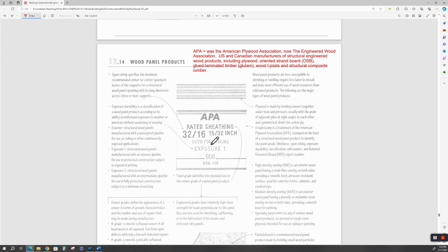So you go buy a half-inch sheet of plywood. Don't expect it to be a half inch. It'll tell you exactly what the thickness is. That's 1/16 of an inch less than a half inch. So when you're ready to make a piece of furniture out of plywood, you've got to take that into account. Which is a pain when you're doing edging, because if you're using 3/4 inch plywood, your rounded molding comes in at 3/4 of an inch. So you've got to cut the molding. You've got to run it through the table saw.